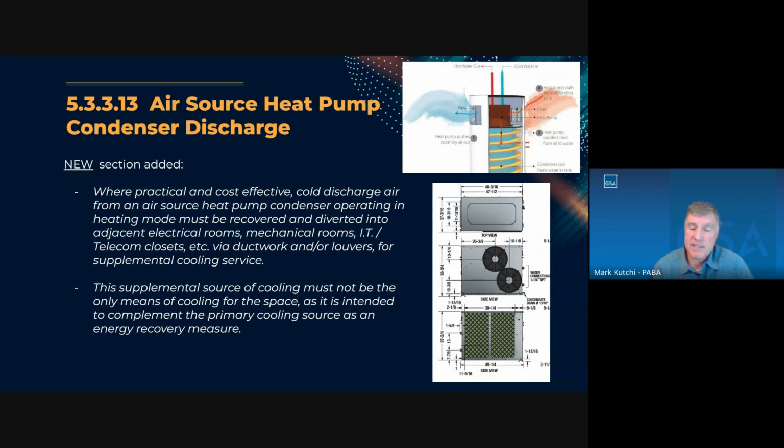So what we'd like the engineer to do is take a look at the amount of cold air that heat pump will discharge and find a way to use it if possible. A large building, especially a large new courtroom or a large new office building with large amounts of large capacity hot water heat pumps, will have a substantial cooling effect. So that could be used for electrical rooms, IT closets, etc.